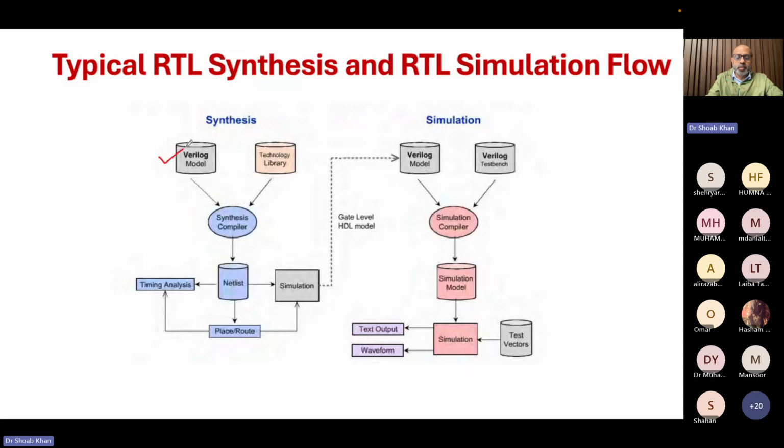So there is a Verilog code for this part. Here's your design, you do a Verilog model, and the test bench is important. So you do the simulation, and a lot of time you spend just simulating, checking, simulating, checking, validating. And once you are happy with all of this, then you say, okay, now I shall send it to the compiler. So here's the compiler, you send it to the compiler to do synthesis.